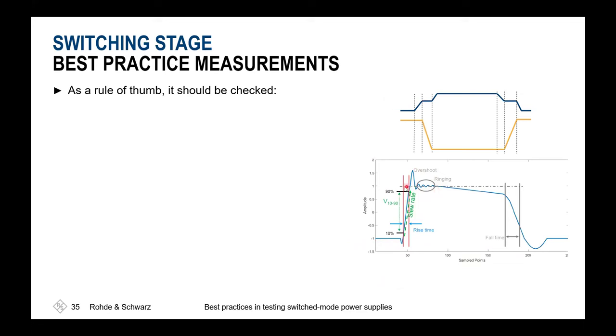So ringing is something where you'll have a very consistent way. So you could draw a line over these amplitudes, and then this concludes to 0. While an overshoot has a very high peak and settles immediately afterwards. So that's a very easy thing to differentiate if this is maybe a ringing, so caused by some resonances inside the system, or if it is an overshoot, so maybe caused by some inductor or other system behavior.